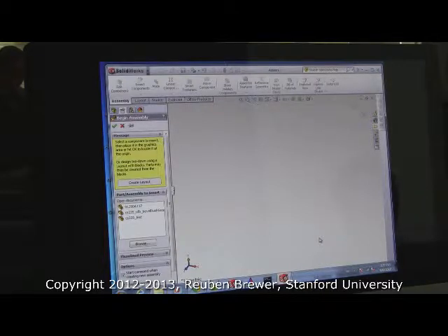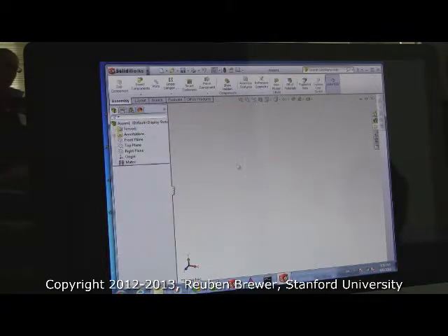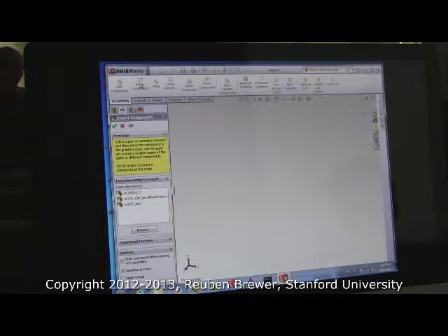Putting parts together. Okay. Go ahead and double, so you see how it says begin assembly? Hit the X on that. So we just have a blank assembly. See this button, insert components? Press that. Now it asks us which parts we want to insert.